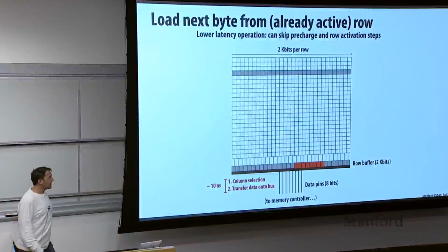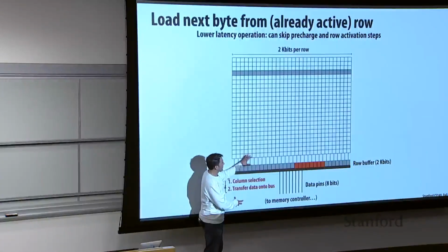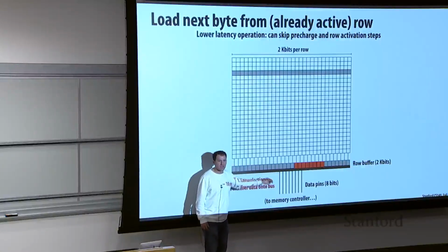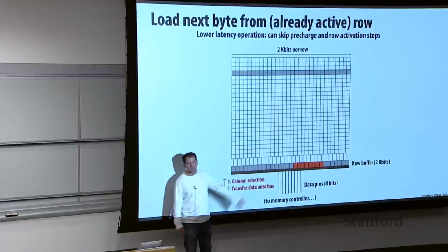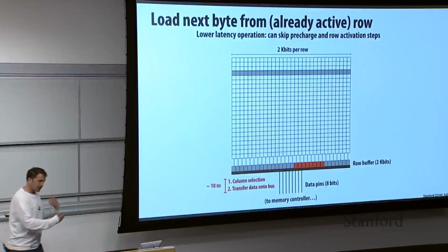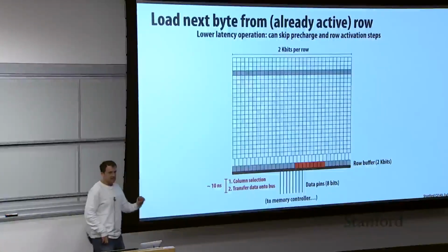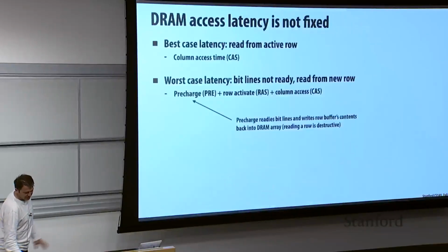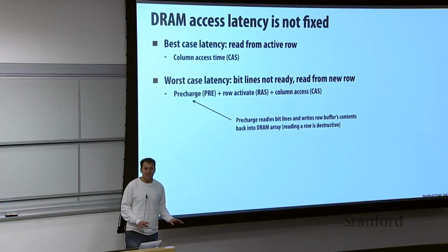This is actually the basic unit of DRAM, and if you want a wider memory bus, you will use more of these. DRAM's got to be cheap because it's kind of a commodity, and so the industry standard is a basic DRAM chip with pin width 8. If you want more of these, we're going to start stacking them, and we'll get to that in a second.